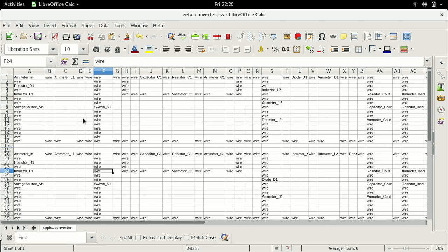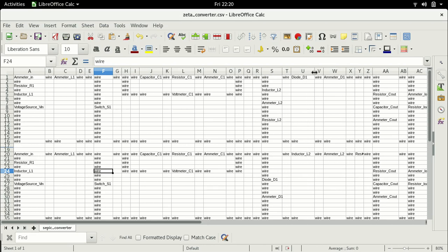of the input. Now, when the current flows in the counterclockwise direction, again, the inductor L2 charges up. So in both cases, when the switch is turned on, inductor L2 is charged, both the SEPIC and the CUK, right? Only difference is, in the case of a SEPIC, the capacitor is not connected to the rest of the circuit. In the case of a CUK, the capacitor is connected to the rest of the circuit, right? The decoupling capacitor C1 is charging the output capacitor and the inductor L2.